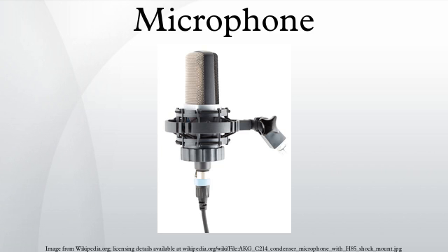Laser microphone. Laser microphones are often portrayed in movies as spy gadgets, because they can be used to pick up sound at a distance from the microphone equipment. A laser beam is aimed at the surface of a window or other plane surface that is affected by sound. The vibrations of this surface change the angle at which the beam is reflected, and the motion of the laser spot from the returning beam is detected and converted to an audio signal.